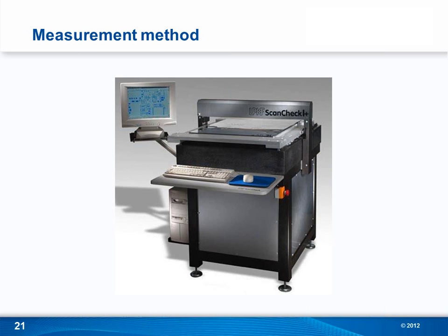And in the bottom of this machine are a number of line cameras. So as the stencil moves below, the light shines through the apertures, gets captured by the cameras, and the computer will then take that information and develop a picture, and at the same time also calculate the size of each aperture and the location of each aperture.